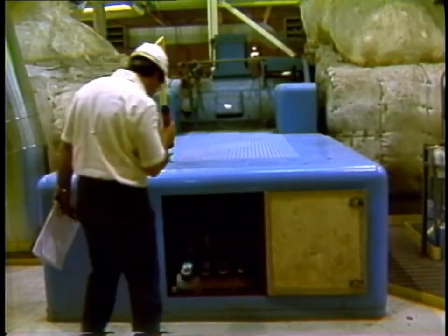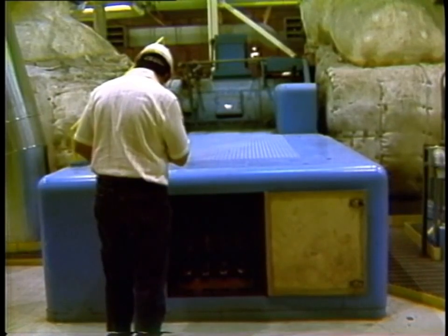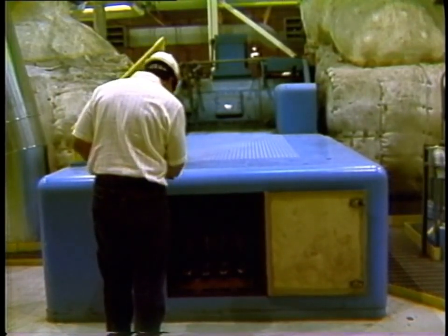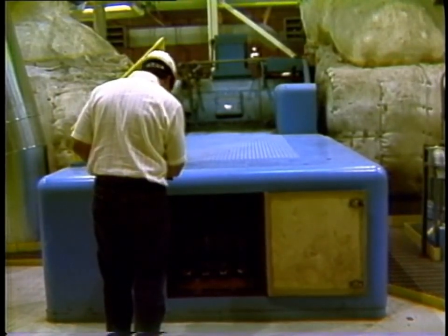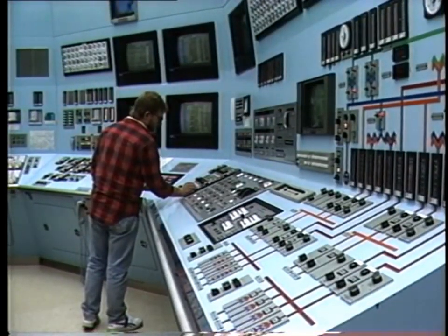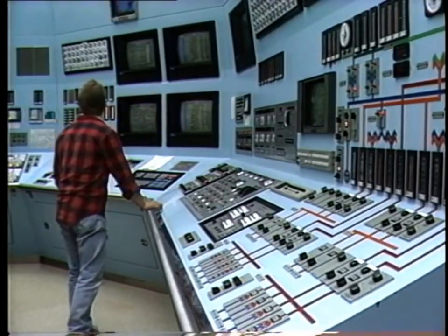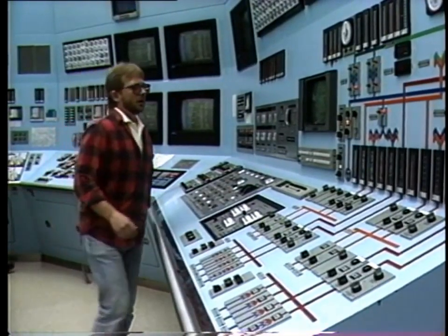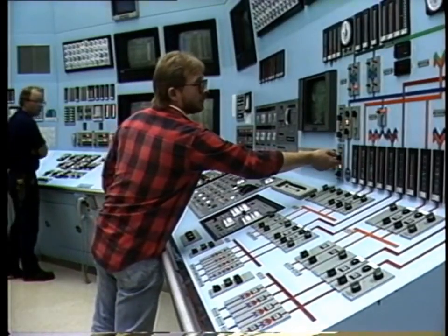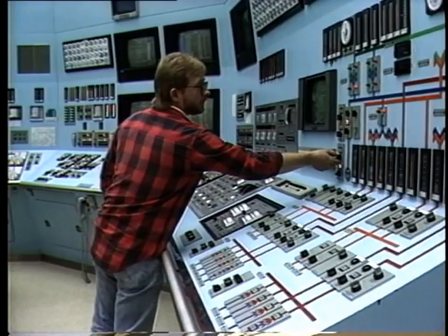Most of the turbine operations are performed remotely from the central control room, with the support of regular local inspection by a roving operator. In traditional control rooms, the operator works at a large panel which includes switching controls, indicating lights, indicating instruments, and recording charts for the complete unit, that is, boiler, turbine, generator, and auxiliaries.